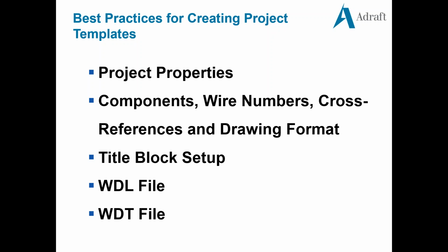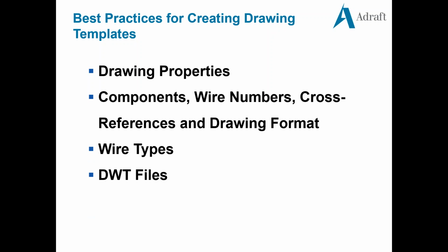Those are two files that you need to actually link and map a title block to a project. We're also going to talk about creating the drawing templates, very similar to your project properties, and they're common between project and drawing. It's extremely important that you build your company standards into the drawing properties.